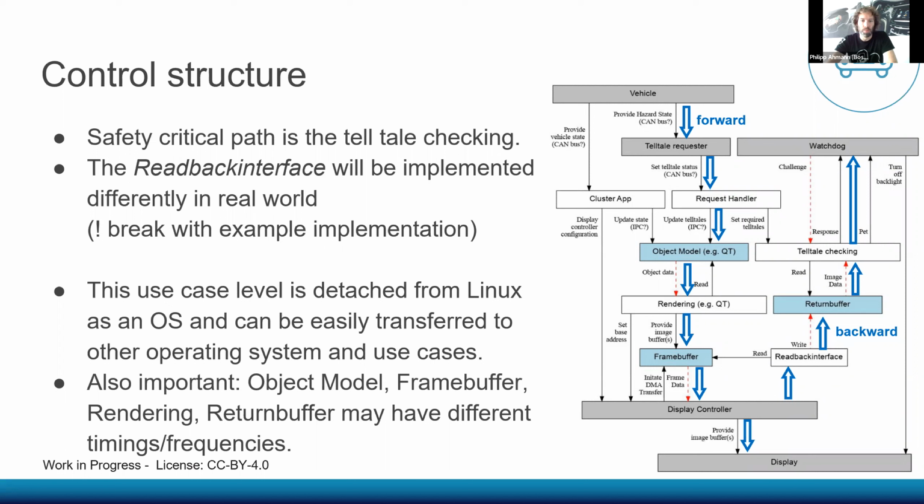Some element which you cannot directly see here, which will give a very interesting part, is the timing constraints, because rendering, readback buffer checking, and display showing all have different frequencies, like 60 Hertz. Some parts may be rendered at 10 frames per second, others maybe even faster than required. So this is something which you cannot directly see in here. The really dynamic behavior is not fully covered.